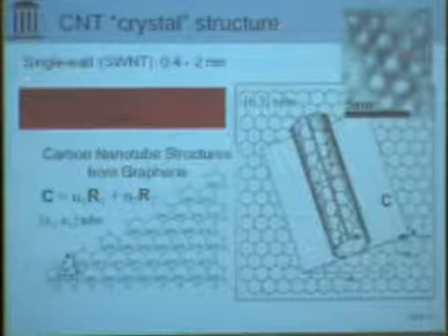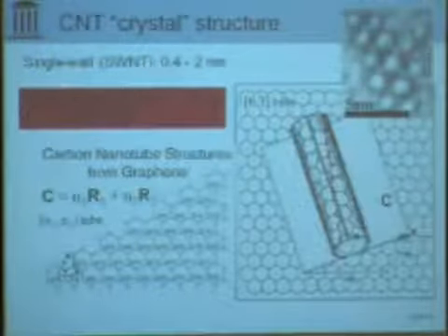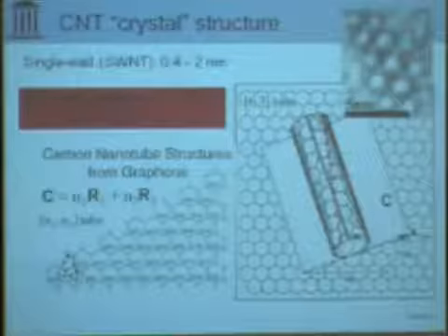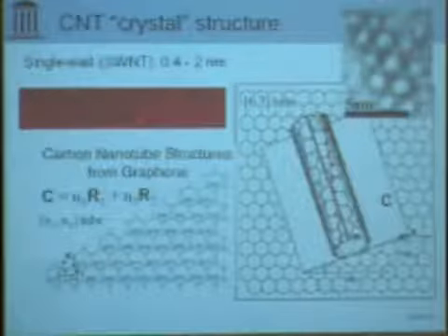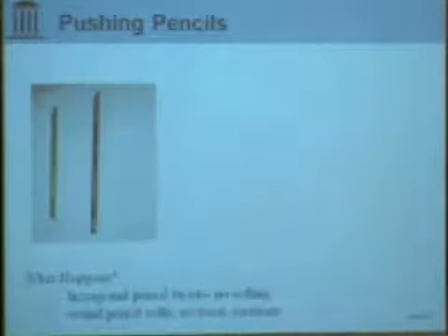One, which will come in the latter part of this section, is single-walled nanotubes. So it's an individual layer of graphite. And you can see our cross-sectional picture here of these single-wall nanotubes. The version I'm going to talk about initially are called multi-wall nanotubes, and these have concentric cylinders. And these are much thicker, 3 to 100 nanometers, than the single-wall counterparts.